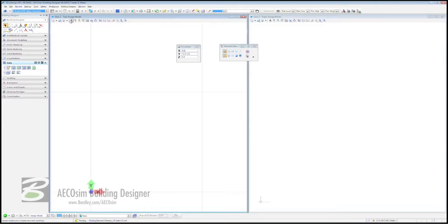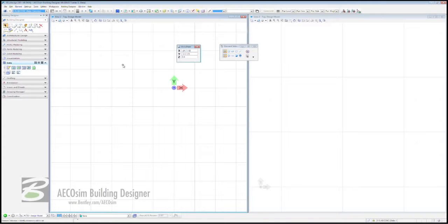We're going to come to our task navigation bar here, and inside that we're going to come to View Rotation. In that we're going to change both of these views to a top view. From there, we can bring in our 2 disparate forms of data, our georeference file and our fledgling structure that we've been bringing on since its inception in conceptual modeling all the way through to this point.